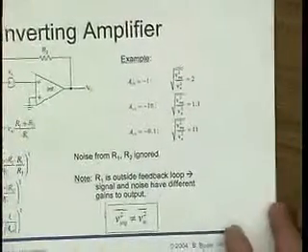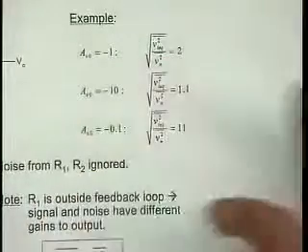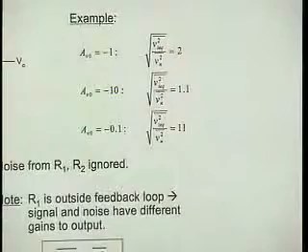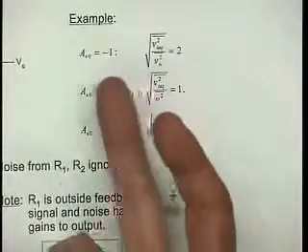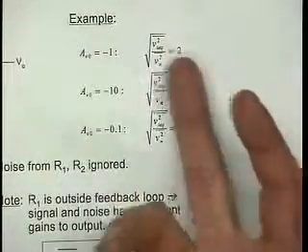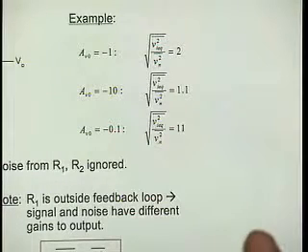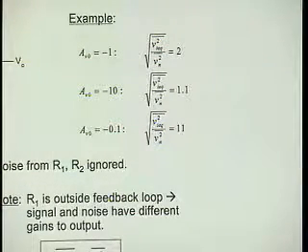If you can use a little bit more zoom again, please. Okay, thank you. All right, so then I went through a bunch of examples. I put in different values for the gain. If I make the gain -1, then I actually double my noise. Because what really happens is that the noise is amplified by a larger gain than the input signal. I amplify my noise more than the signal, and consequently, my signal-to-noise ratio is going to suffer. Well, of course.